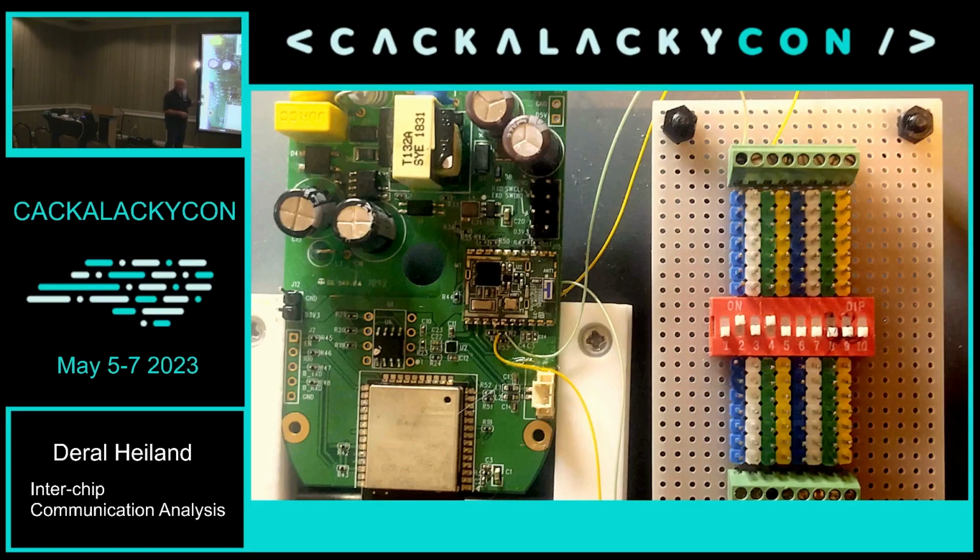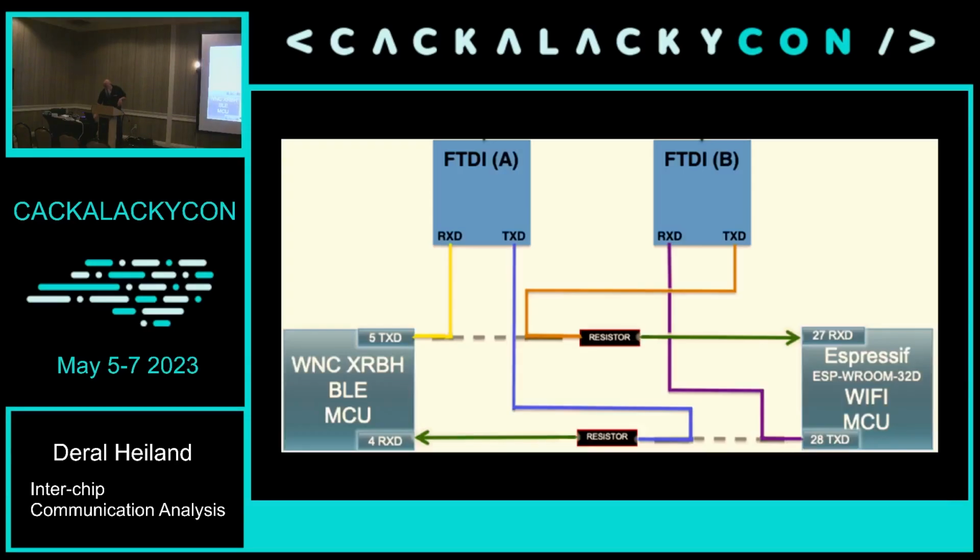This is how we started off early on in this particular project, but we took it to a new level later on, and we'll actually talk about that later. In this case, I did most of the testing very manually. I hooked up some FTDI devices. So this is how we tapped into the two FTDI devices. And then I was able to catch the communications, open and close the circuits with a switch, and transmit and receive data or manipulate data inside the circuit.